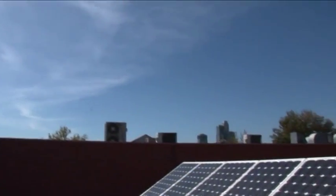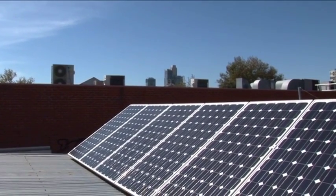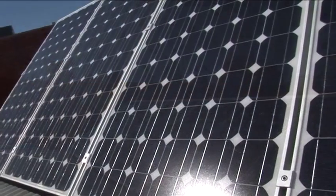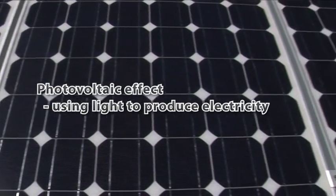If the photodiode is not biased, that is, it is not connected to a power source, then a voltage builds up inside the diode, leading to a current flowing. This is the photovoltaic effect, which occurs in solar cells.